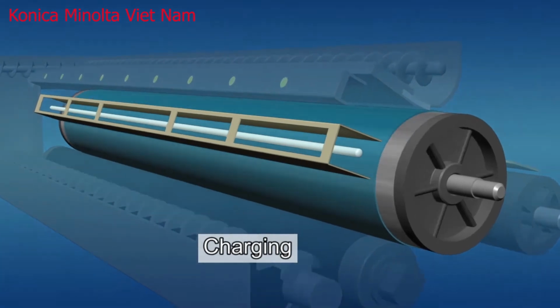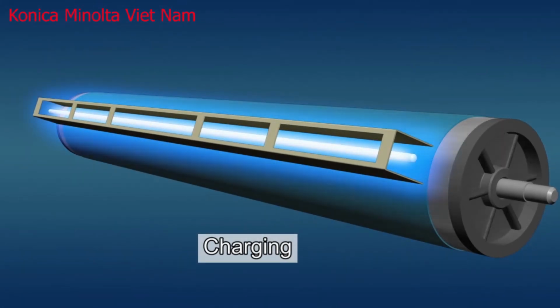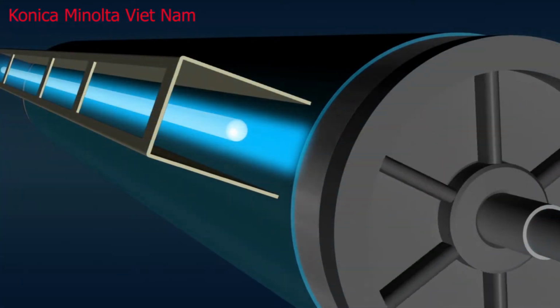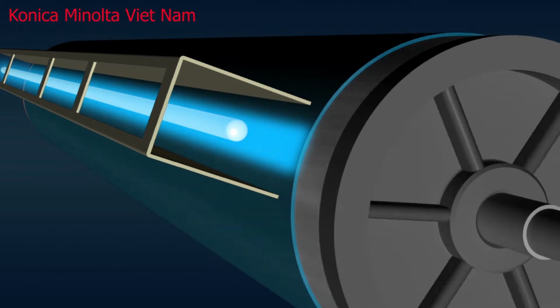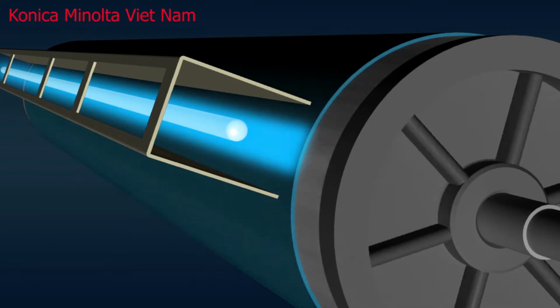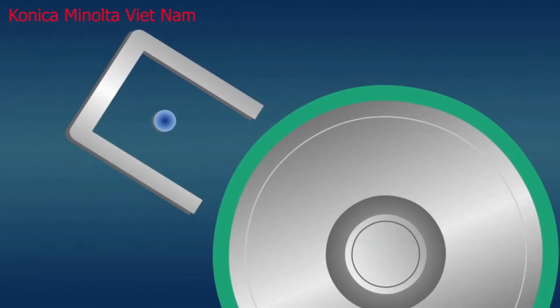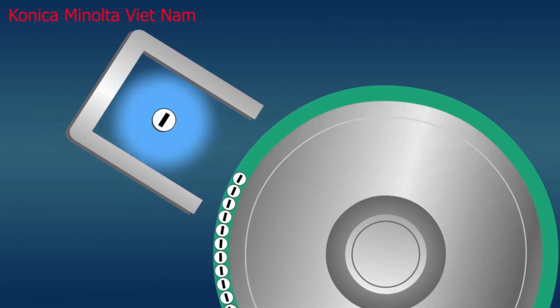The charging electrode is the first component to affect the drum as it rotates in darkness. High voltage of minus direct current is applied to the electrode, which emits a corona discharge. The corona discharge ionizes the molecules in the air, thus charging the entire drum surface with minus electricity.